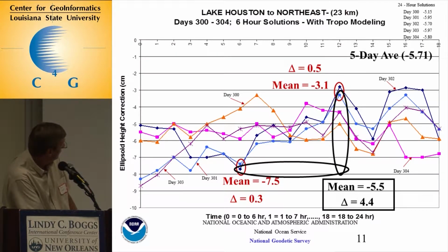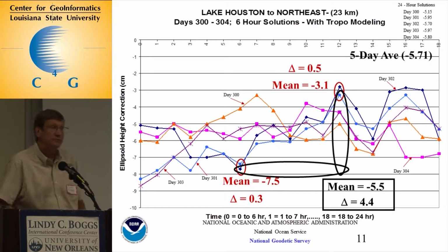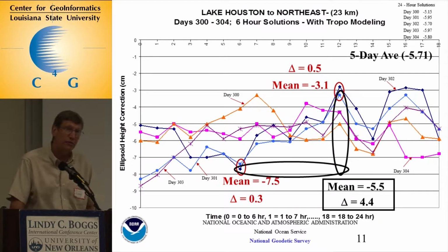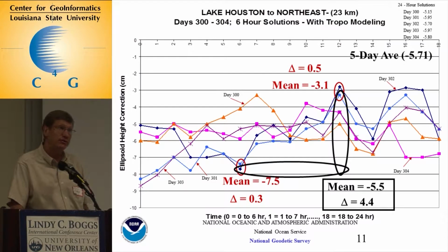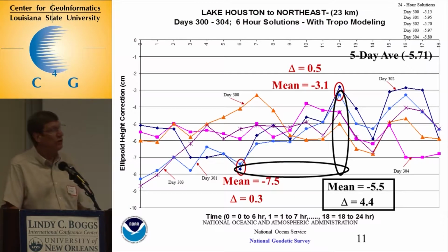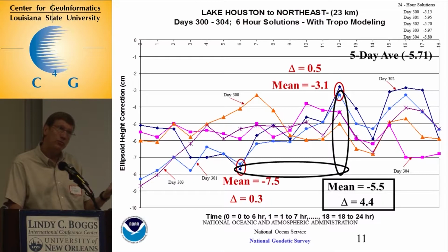It's minus 5.5. And look what I think truth is. So we were looking at this and saying, well, you know what? If we can repeat these over a couple days, different times of the day, then I take into account some of the geometry change of the satellite, some of the multipath going on, some of the atmospheric effects, all which cause some problem of the data. And that was what we're after.